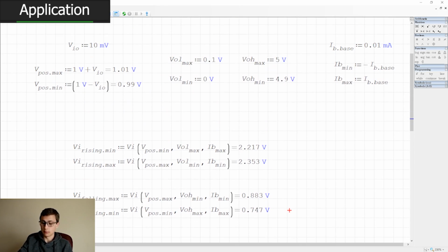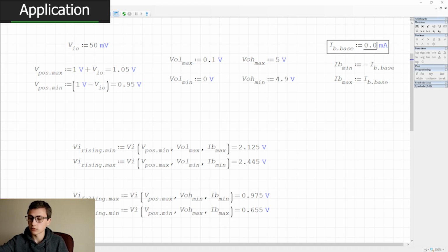Now let's say, for example, you have a slightly different comparator. Anyways, so let's say you have a different device that has a different input offset voltage, and you're like, okay, what if it was 50 millivolts instead? You can plug that into your spreadsheet, and immediately that flows down into your thresholds. You can see the impact that has, and you're like, okay, well, what if we get a cheaper comparator that has more bias current? And let's say that goes up by a factor of 4. What would that do to our system? Wow, that has a pretty big impact. That shifts things around quite a lot.